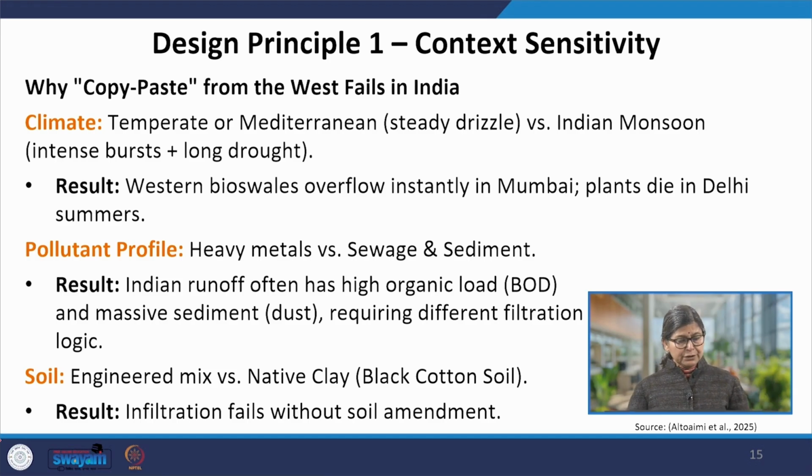Similarly, for the pollutant context, the pollutant profile is different. Heavy metals versus the sewage and sediment. Indian runoff often has high organic load, BOD, and massive sediments, dust, requiring different filtration logic. Soil, in case of India, is native clay, black cotton soil, whereas we are actually competing with the engineered mix. Infiltration fails without soil amendment.